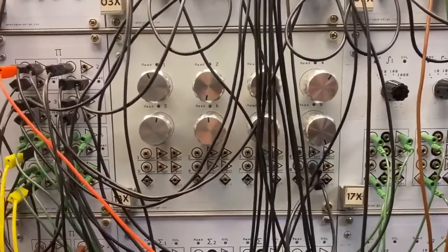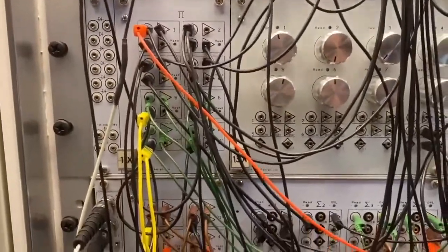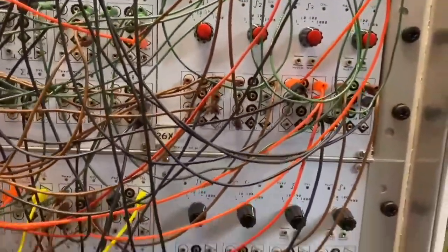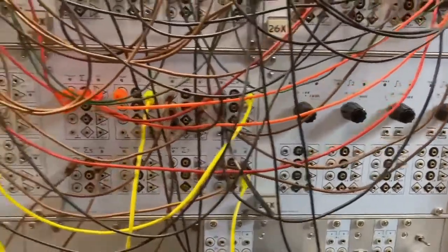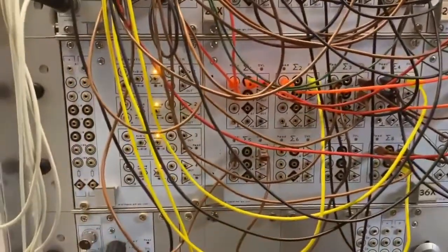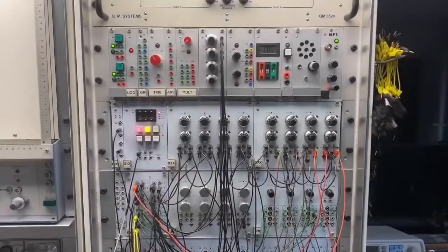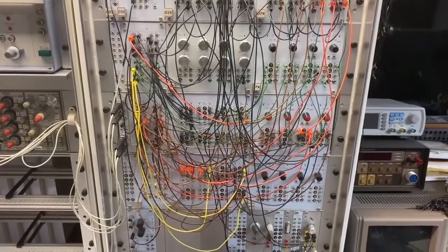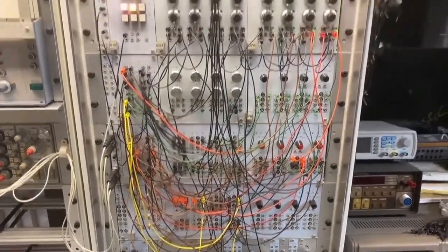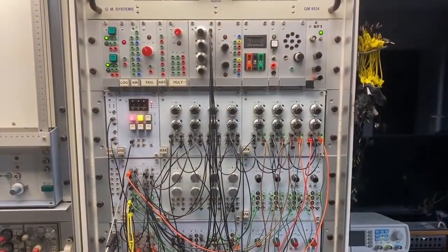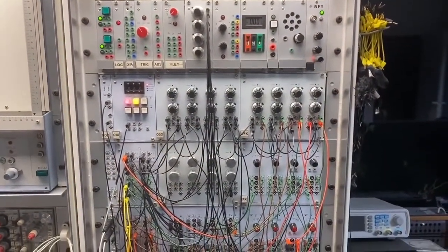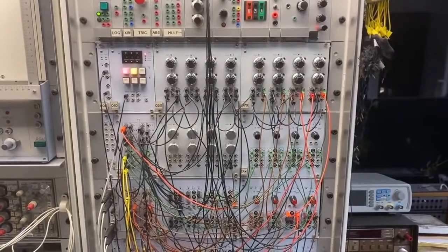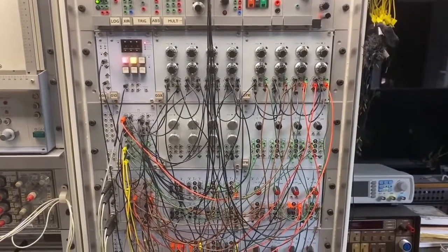Here you have another module with 8 manual potentiometers, 8 multipliers, another 8 multipliers, 8 summers, 4 additional integrators, 4 other integrators, 8 summers, and a quad comparator module. The program you see here is much more involved than the basically pretty simple Lorenz attractor or Chua attractor program. What this program implements is the simulation of a chaotic double pendulum. So you have a pendulum rod which is mounted to the tip of another pendulum rod which is mounted on some pivot point so it can swing freely around.